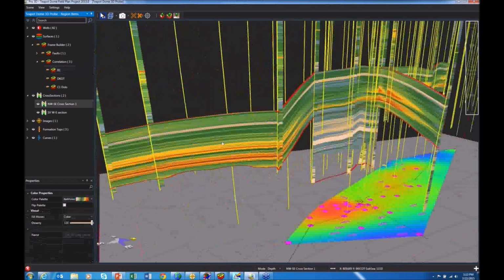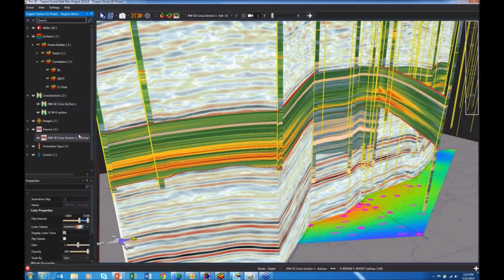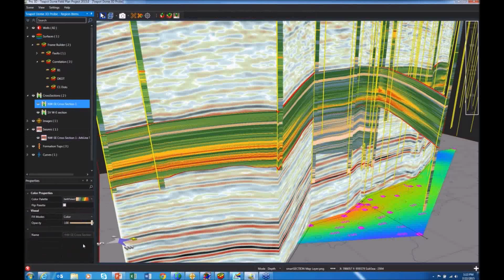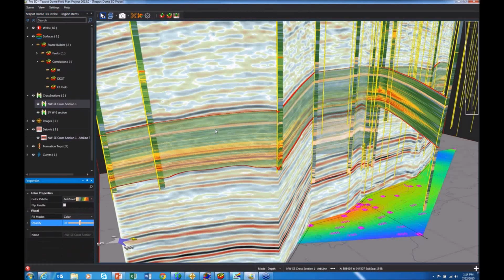I'm also able to select that fence diagram and display the seismic behind it, and then use the opacity control to blend back the petrophysical attributes against the geophysical attributes. Now currently I'm just showing the amplitude attributes, but if we had done some post-stack processing using LMKR's volume attributes, I could do an ESP, a curvature, and any number of other attributes that I could blend back and forth between the two to see what kind of influence the seismic and the geophysical parameters have upon one another.